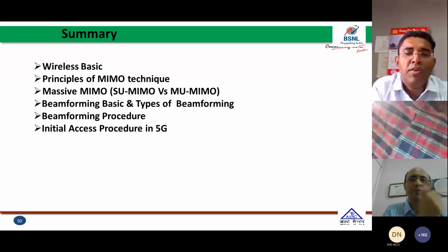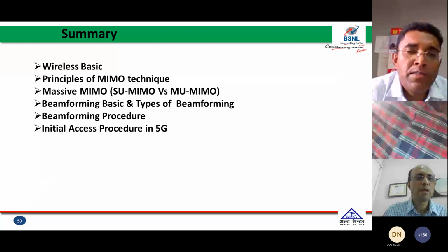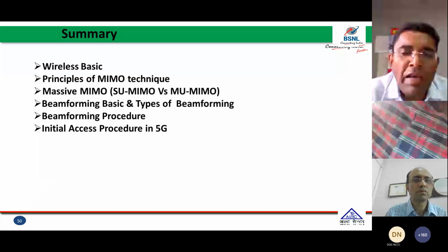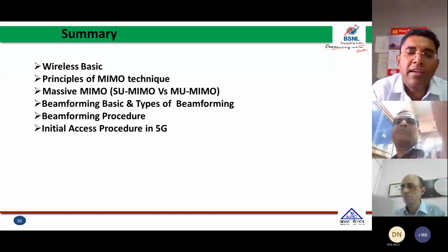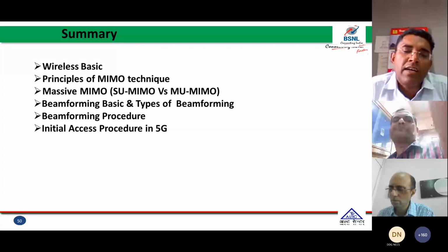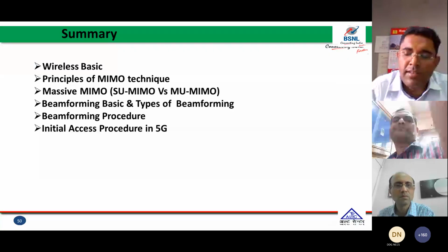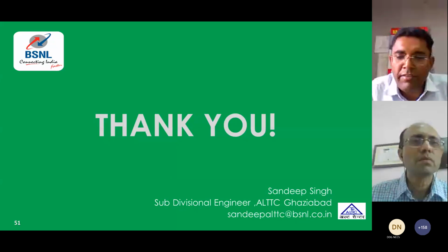Okay, sir, thank you. In summary, we have studied today the principles of massive MIMO and some wireless basics. Then massive MIMO in TDD mode, single-user MIMO and multi-user MIMO, beamforming basics and the procedures of beamforming, and then the initial access procedure. We have discussed all of this in this session. Thank you to all. If you have any question, then please ask.